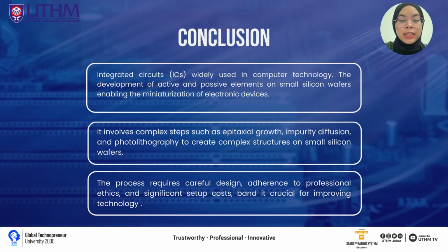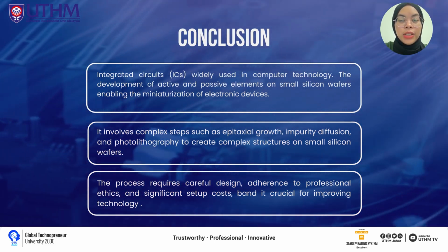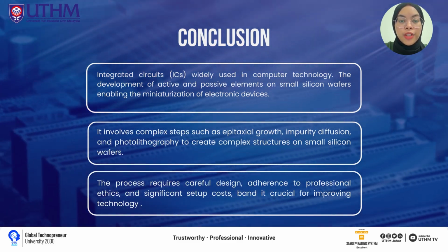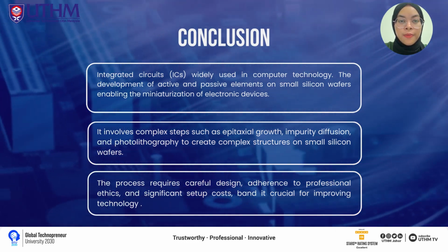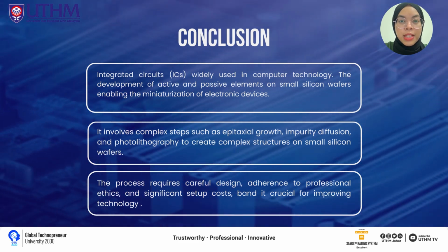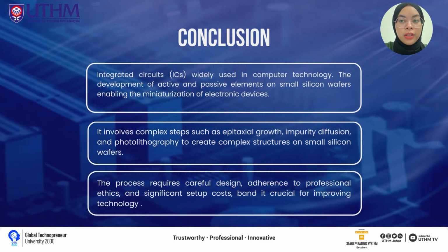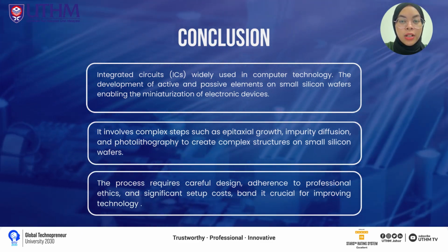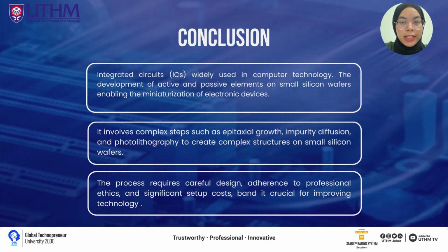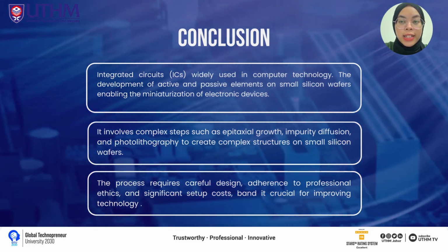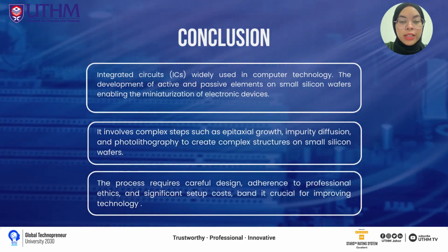In conclusion, the integrated circuit is widely used in computer technology. The development of active and passive elements on a small silicon wafer enables the miniaturization of electronic devices. It involves complex steps such as epitaxial growth, impurity diffusion, and photolithography to create complex structures on a small silicon wafer. The process requires careful design, adherence to professional ethics, and significant setup costs, but it is crucial for improving technology.